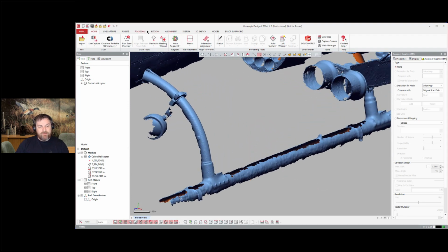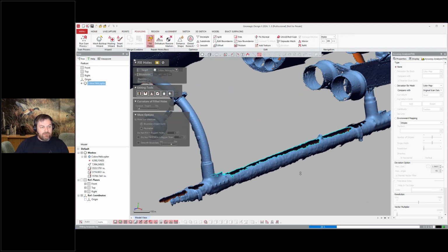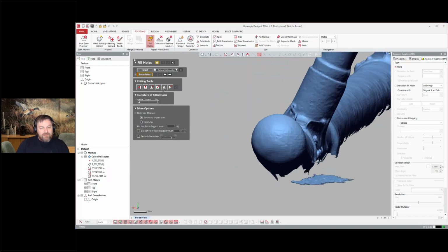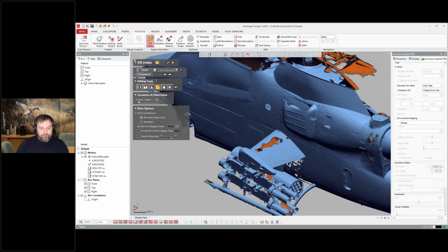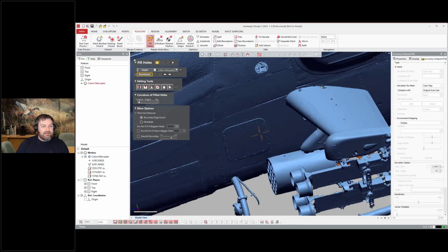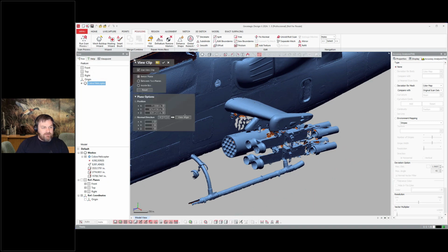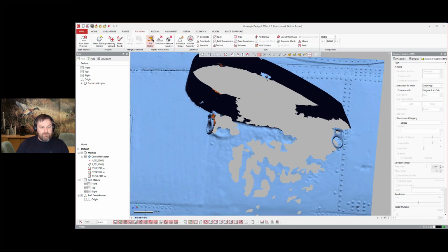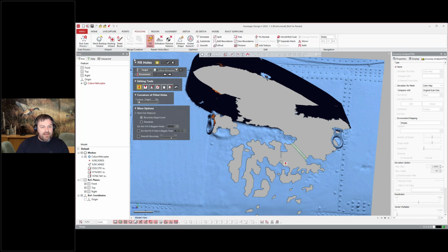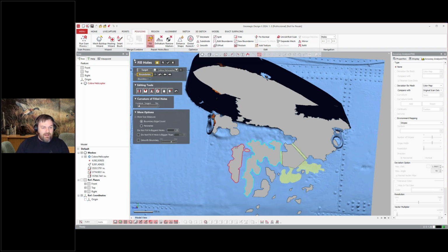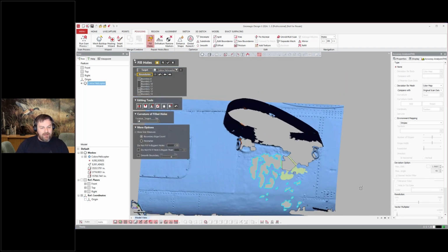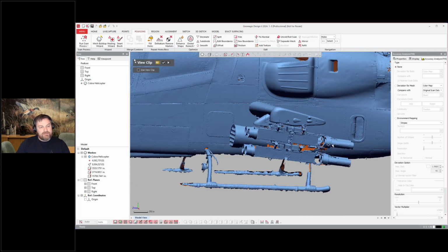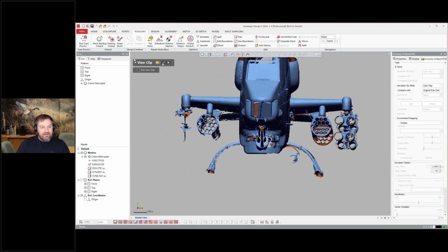Now in Design X, I have the ability to do some scan editing as well. You have a little bit of that in the Scantech software, or you can also do that inside of our software. Sometimes I breeze over this, so I wanted to highlight it today. While you may sometimes miss an area, obviously the ideal is to go ahead and scan. I selected some areas to show that we have the ability to hole fill, and to hide and show strategic areas of the mesh and almost do surgery on an area. Kyle and his crew scanned the majority of it, but this is an often overlooked aspect of the software: even if you weren't able to get enough information, you're still able to work with it inside of Design X and edit it in a lot of different ways.